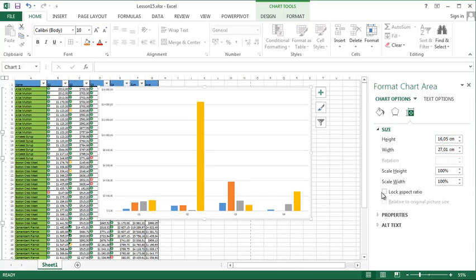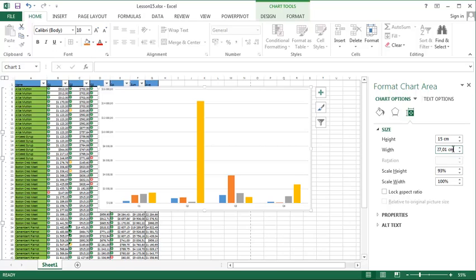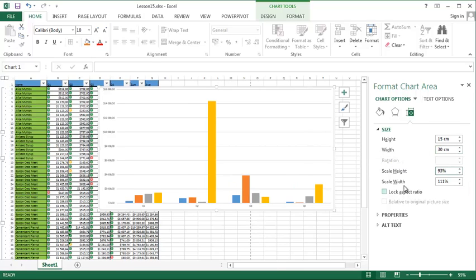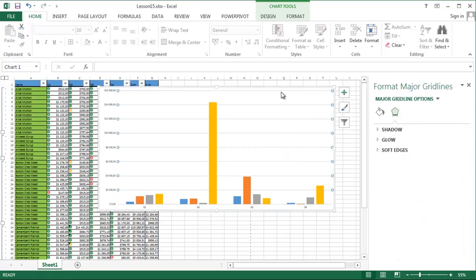Okay, next off, let's use some, maybe not 3D. Let's change a bit of the lock aspect area, but first off, we need to change it to 15 centimeters times 15, so 15. And also over here, we will use 30. And we will lock the aspect ratio, so right now, if you try to change anything by hand, it won't change at all.